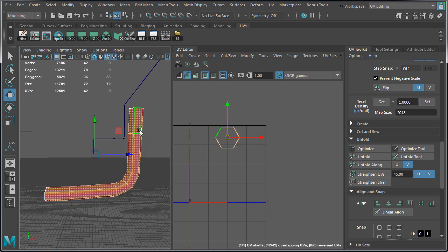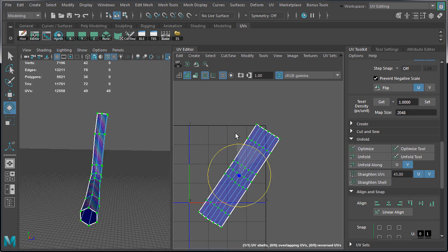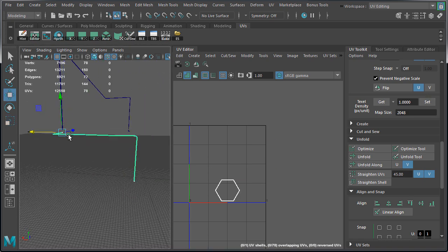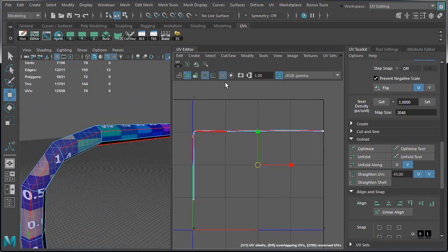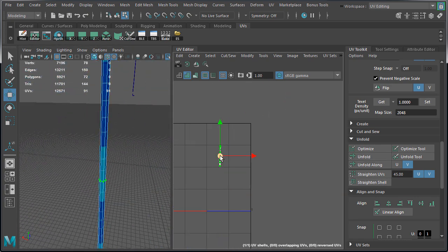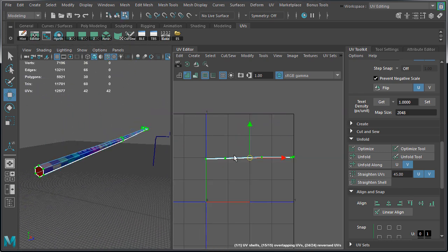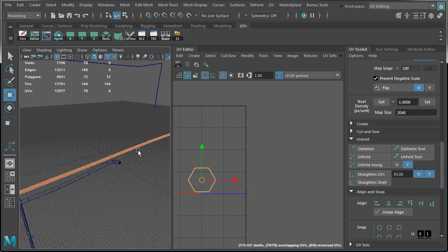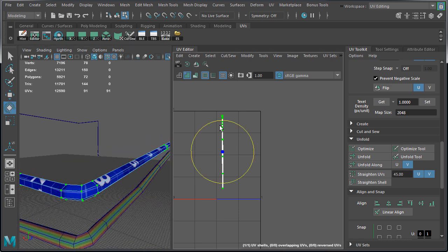So I'm going to quickly run through the steps and UV all the wires. Selecting the faces, projecting on X, Y, or Z, choosing an edge where I want to make a texture seam, make a cut, unfold, straighten shell, and set texel density. Then move it out of the way and move on to the next wire. And this is incredibly fast, especially for some of the more complex wires that wrap around the building. And with the updated editing tools that were introduced, I believe in Maya LT 2016, in one of the updates, UVing this becomes almost effortless.